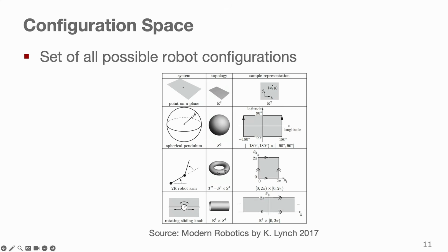And so this is kind of important because when we train our neural network to be a policy, the network has to respect the different topologies that your robot configuration space has. So for example, in the torus case, the distance between 2 points is not always a straight line, right? If you're at 356 and you want to get to 1, the shortest path is just 5 degrees and not going back 355 degrees.